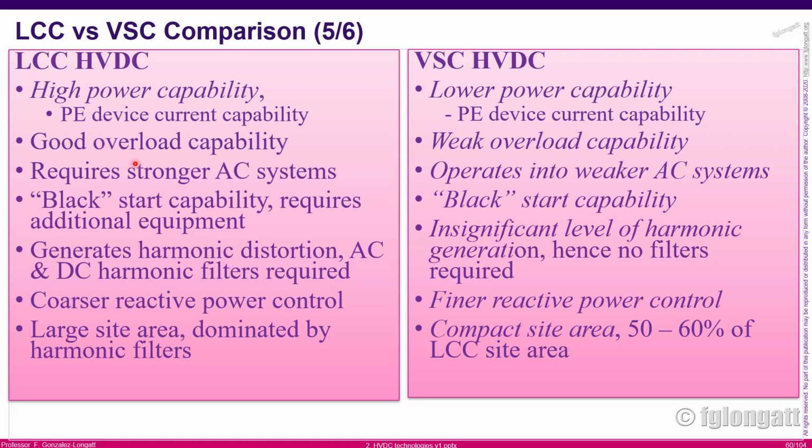I mean, they must be connected in a place inside the power system where you have a lot of transmission capacity and very high short circuit levels, okay? One of the problems of LCC, they don't have the capability of black start, okay? That means if we have a total blackout, those devices cannot restore the system, and that is a very, very bad drawback of them, okay?